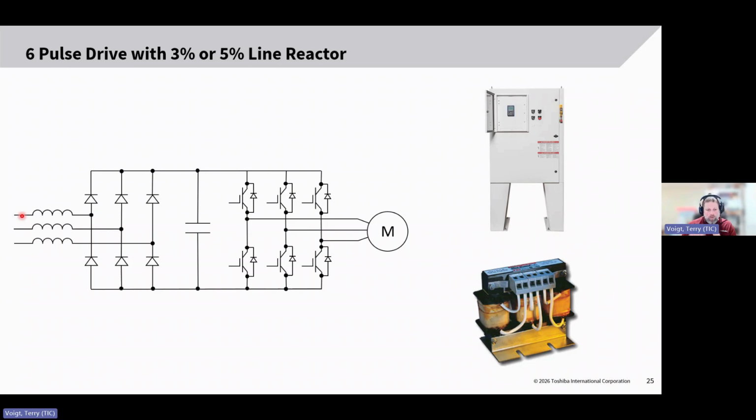So yeah, there's kind of a dual purpose for that, right? It can help reduce harmonics, and it also helps with any voltage transients, because the voltage can come along this way, and then there's an extra device. It's almost like a transformer that it has to go through before it gets to the drive. So that's ultimately on a 6 pulse type of configuration.